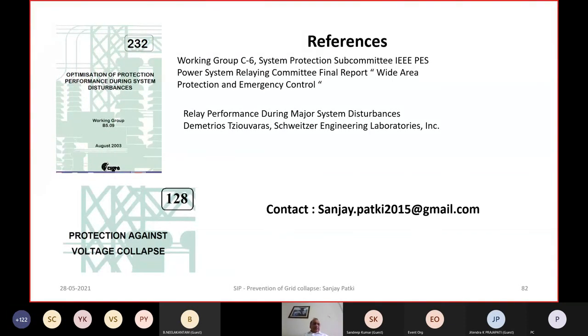So as we were discussing yesterday, either this can be detected through negative sequence protection or current unbalance monitoring on the SCADA system, and action can be initiated manually by opening the pole, or isolating the breaker by opening of the other circuits.